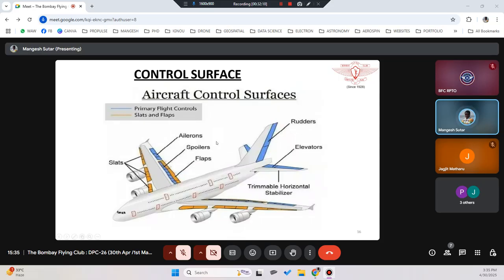Okay, so now as we are talking about the aeroplane, let's see what control surfaces are there on the aeroplane. Now these are very important when we are flying drones, especially the aeroplane type of drone, or maybe even in drones also. Let's see how these are applicable. If you see the aeroplane, there is a round structure which we call the fuselage, and you will have two wings on either side. These wings will have control surfaces which are called ailerons. These ailerons create the shape of the wing for flying purposes, or the lift purposes. The ailerons are on the wings.